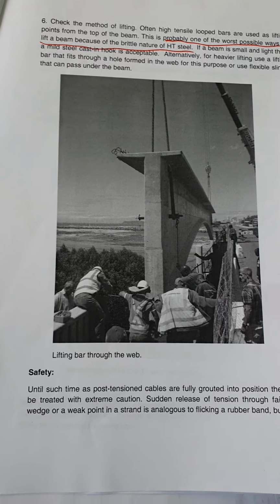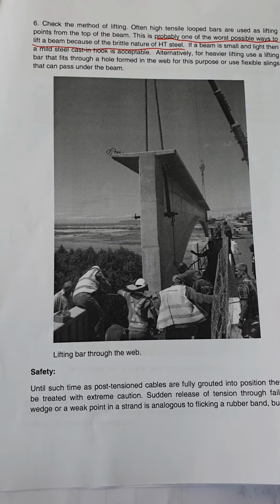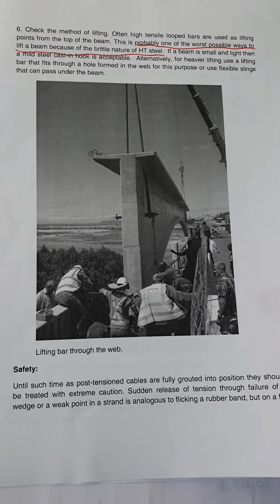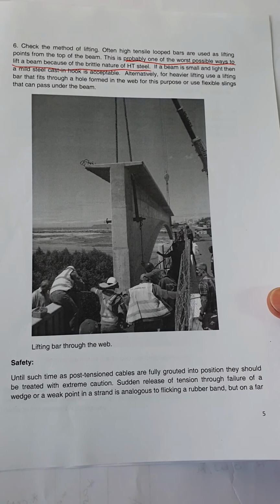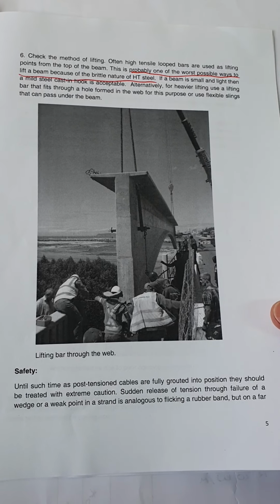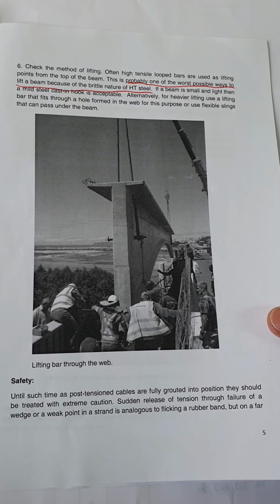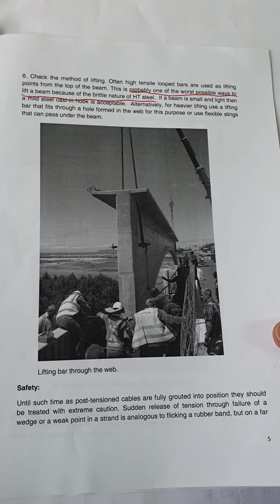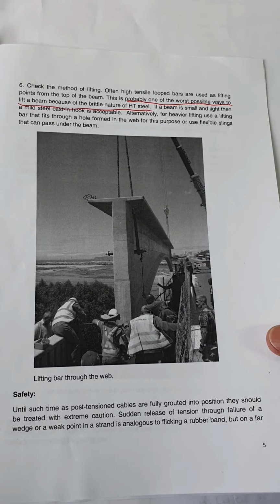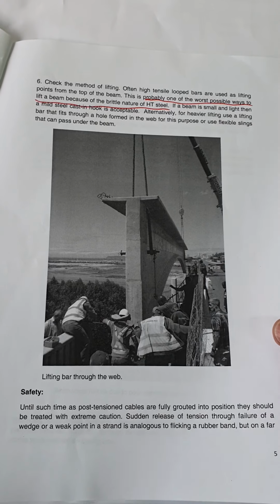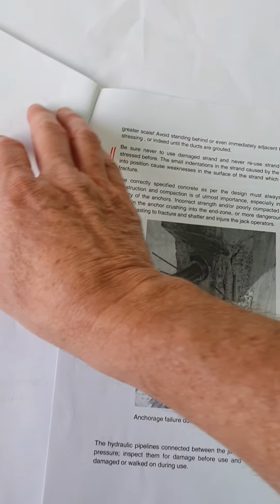Okay, one or two safety issues we need to just talk about. Until such time as the post-tensioned cables are fully grouted into position, they must be treated with extreme caution. A sudden release of tension through failure of a wedge or a weak point in a strand is analogous to flicking a rubber band, but on a far, far greater scale.